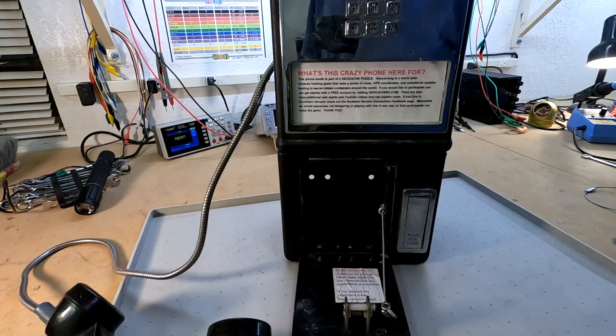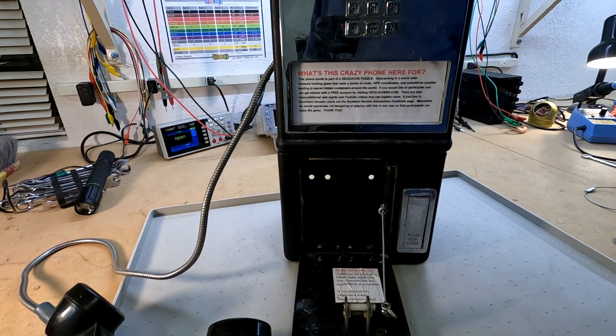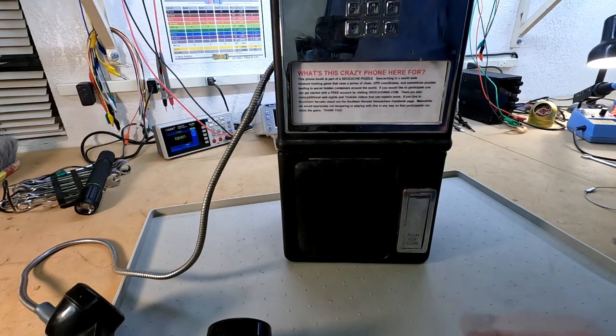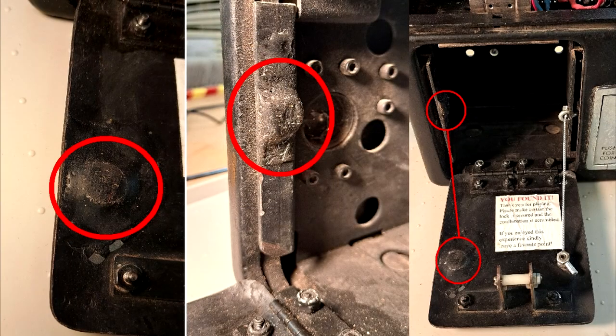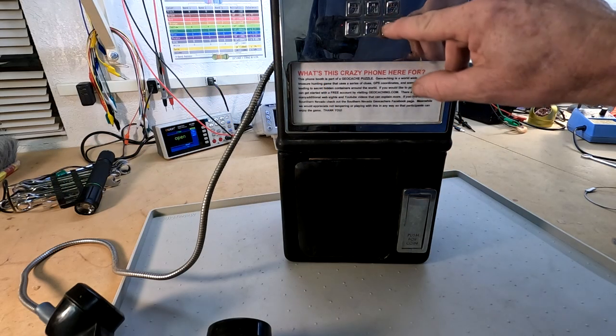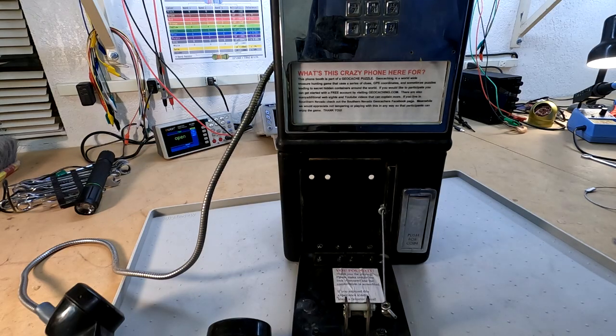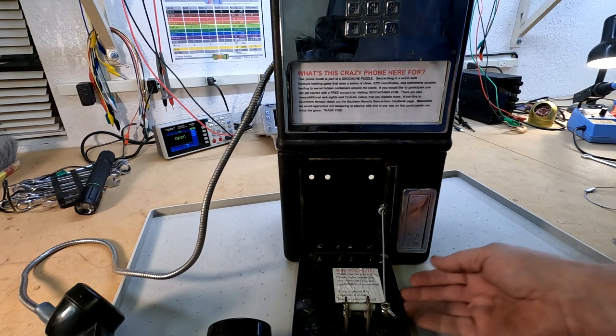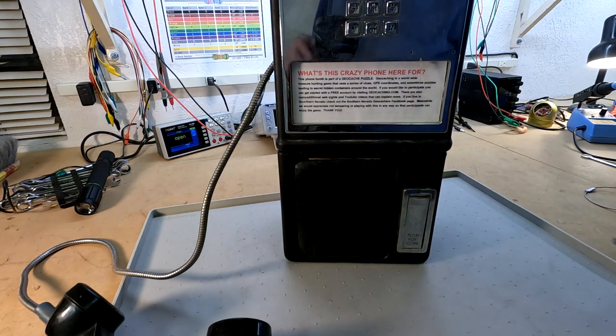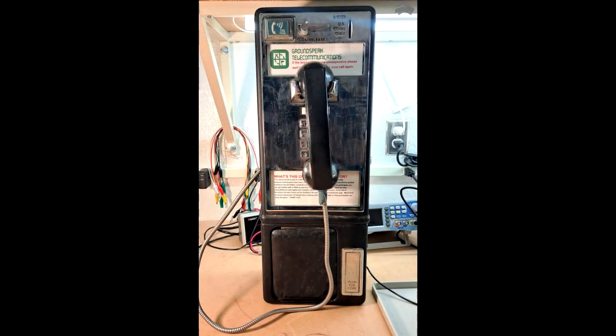Because the door is vertical, it needs some outward pressure to push it open. After some experimentation, a spring was found to be impractical. Instead, 2 neodymium magnets were used. They were oriented so that they opposed each other. They were attached with epoxy and fiberglass to securely hold them in place. When the door is closed, the opposing magnets provide the necessary force required to push the door open when the latch is released. Finally, all the screw holes were filled, and it was painted black to match the phone. If this is all done correctly and carefully, it looks almost original when the door is closed.